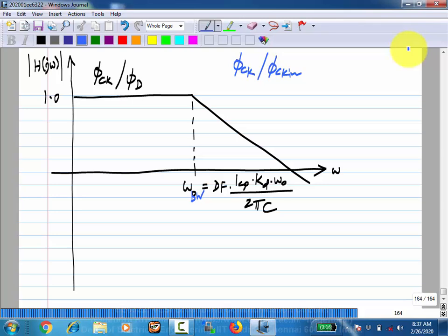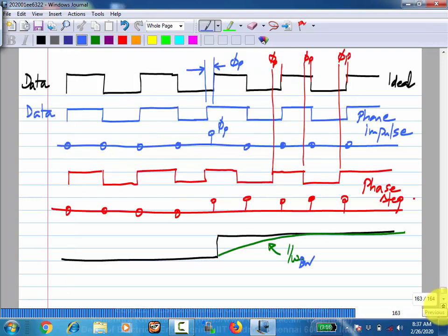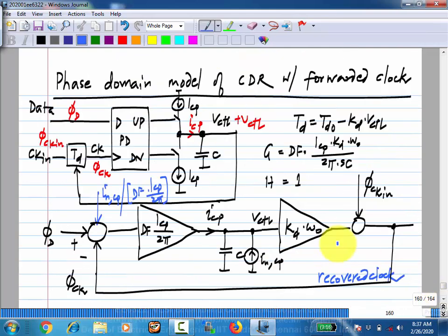Band first, high pass. So it will be just a complementary curve to this, and it will have the same corner also. And this has a high frequency gain of 1 and some corner like this. Now why does this make sense, this being high pass? If you look at this, what happens? High frequency?